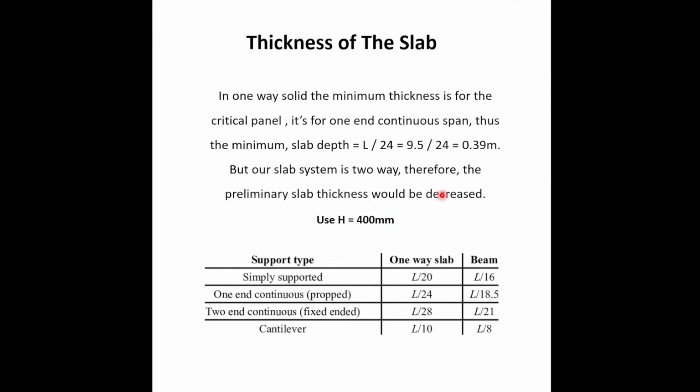Note that this table is for deflection consideration only. So maybe the loads, if they are high, may affect this thickness. So we use a starting point for H equal 400 millimeter for the whole slab thickness.